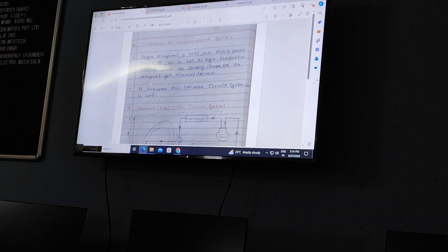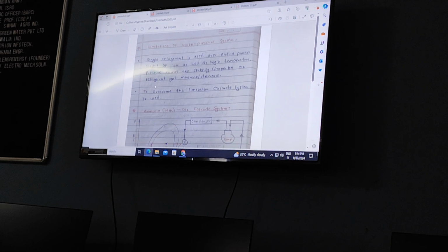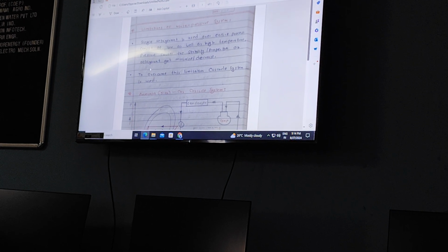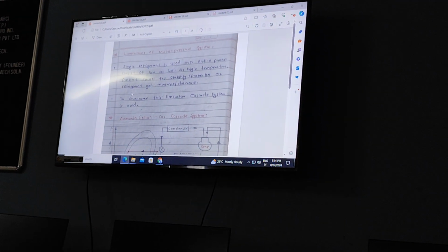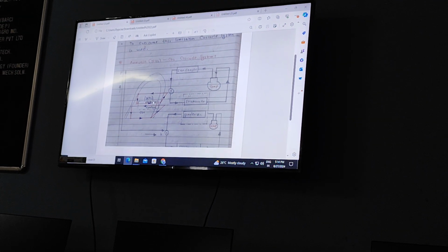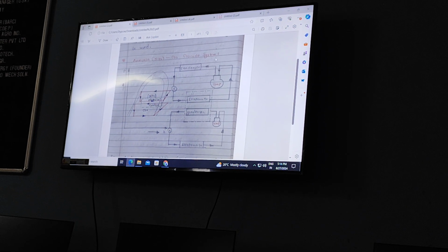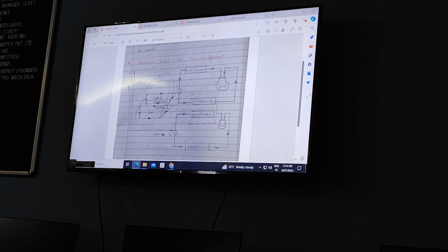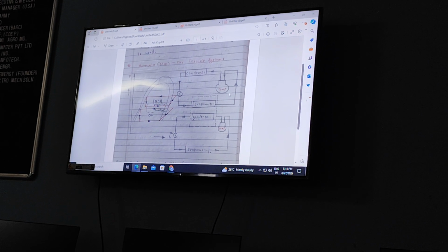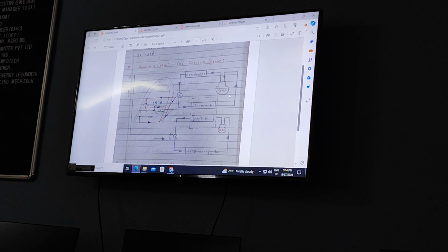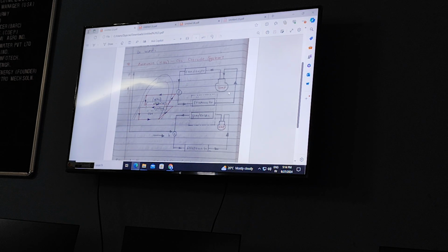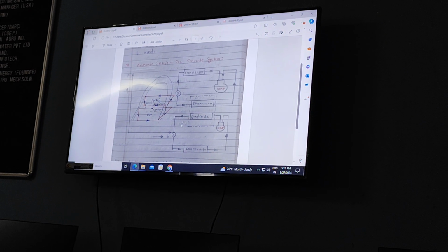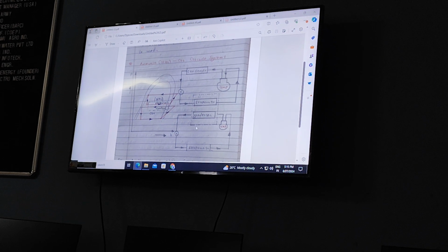In the cascade system, we combine 2 separate systems, using 2 separate refrigerants: ammonia and CO2. You can clearly see the schematic diagram here. The upper diagram is of NH3. NH3 is toxic, so we cannot use it directly for food, but CO2 is not toxic, and CO2 is a very good refrigerant on the lower temperature side.